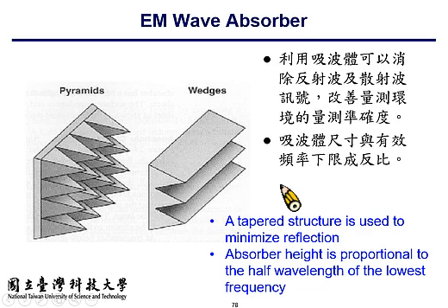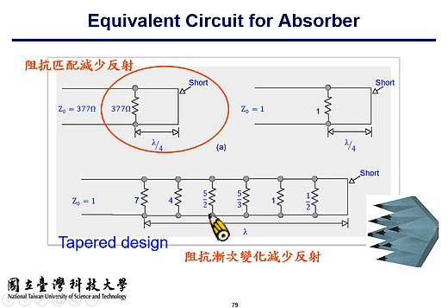500 megahertz, because the wavelength of 500 megahertz is 60 centimeters. So if you have an absorber of 30 centimeters, then you're supposed to absorb electromagnetic waves down to 500 megahertz. Okay? So the bigger the absorber, the lower its effective absorbing frequency. All right? And due to the time limit, I will just say that this one is referred to as the